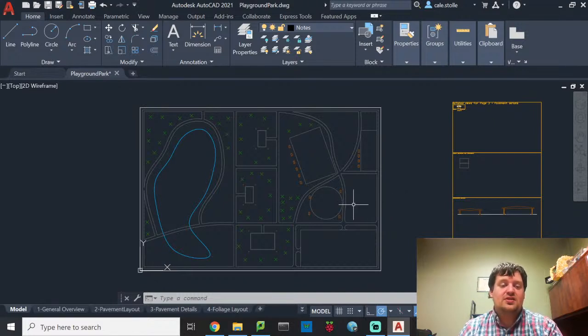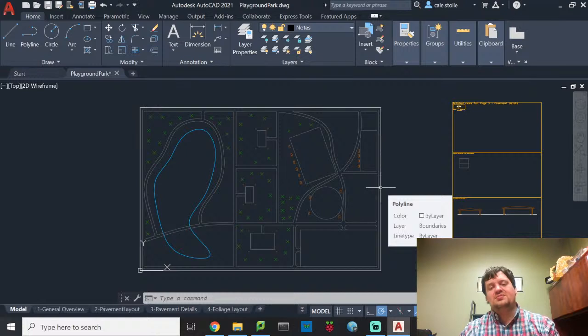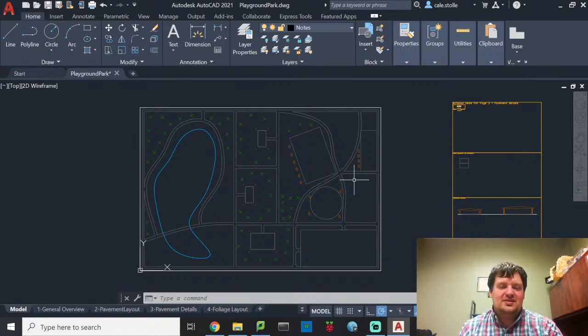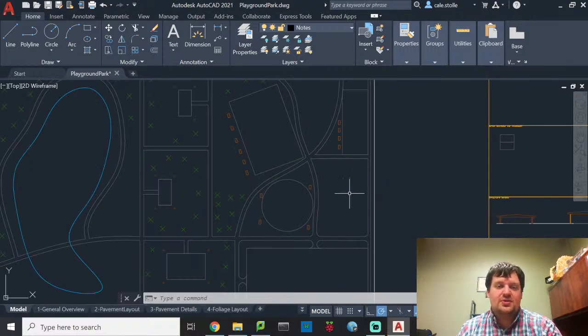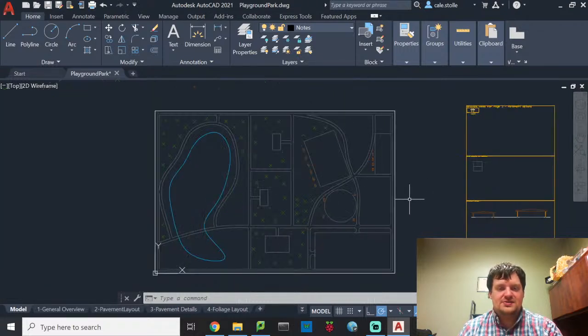It doesn't require shutting off the sewer. It's really easy to connect into an existing connection. Otherwise, you have to cut the pipe, replace a section of pipe, seal the pipe. It's kind of a hassle. So if there was an existing connection, we would want to connect to that. Here, because this is a theoretical park, we're going to assume that there's no existing connection point. We're just going to have to connect to the sewer as it is.